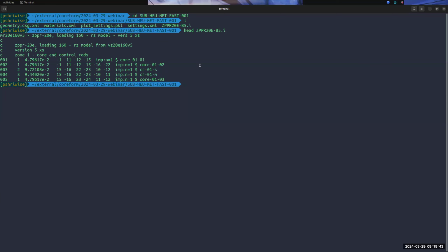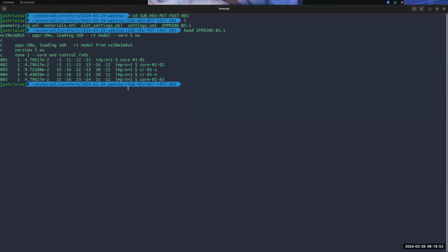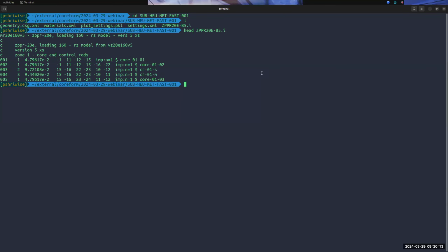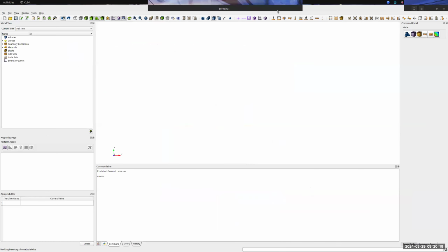Yep. Great. So again, this is the text-based format of the MCNP inputs, and they are not necessarily human interpretable. For example, this line tells you that this is a cell definition and that it occupies space on certain sides of these different surfaces with a material and a density. But that's not something that you would naturally read and understand if you were not familiar with these input syntaxes. So let's move this into something that's a little bit easier to understand.